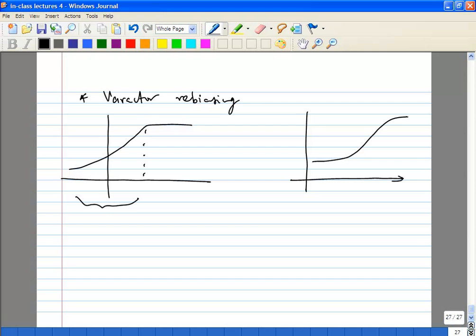Because the control voltage is being produced by some kind of circuit which has only 0 and VDD, you can't afford to have negative voltages. So you're basically losing that much of tuning. If you want to make it up, you'll just have to rebias your varactor, no other go.